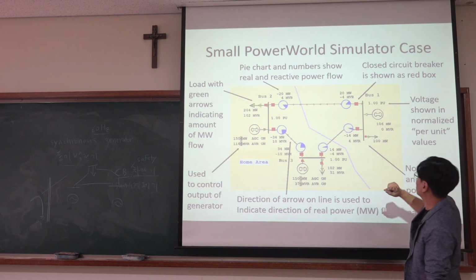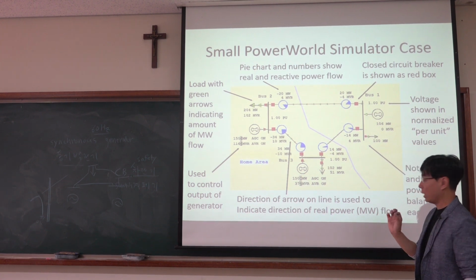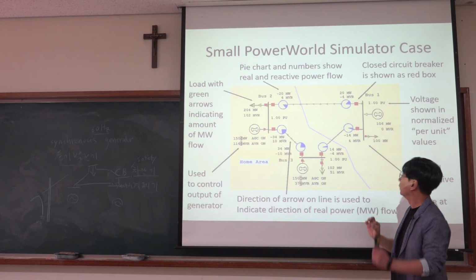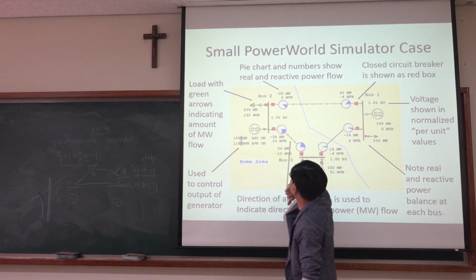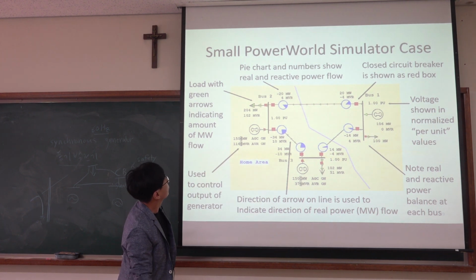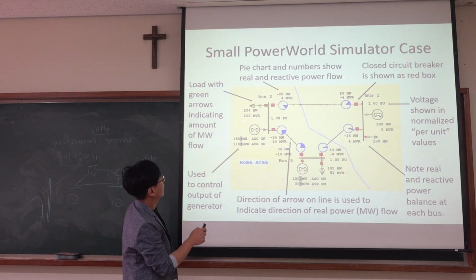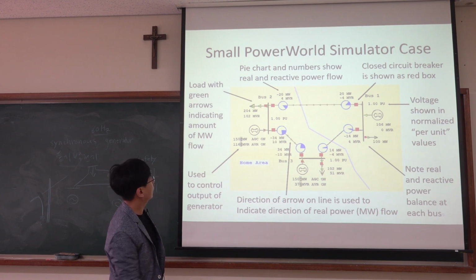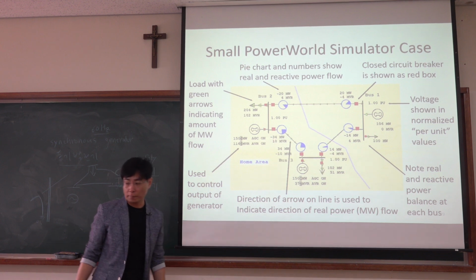So the power injection is outgoing power is 60 minus 6 plus 100. That comes from here. Okay? And you can check also here. Generation is 150. So it is consumed 204, but then there is a deficit of 54, and that is from this line and that line, so minus 20 and minus 34, okay?